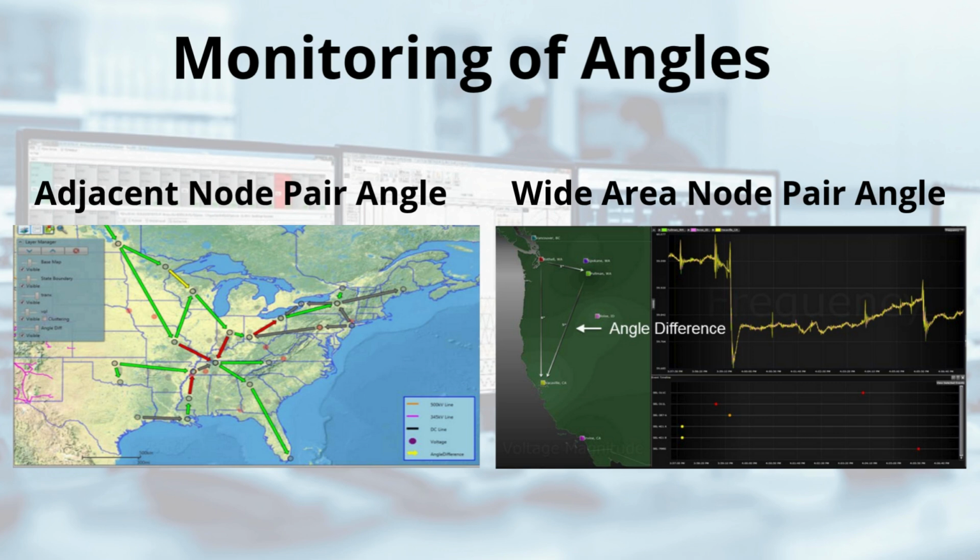It allows them to make adjustments, maybe change generation or line flows when there's a disturbance. And critically, it ensures we're operating within safe limits, not pushing things too far. And the source seemed to really emphasize power angle monitoring specifically for system operation. It does, yeah, and rightly so, because power angle speaks directly to system-wide stability, those potentially dangerous inter-area oscillations.